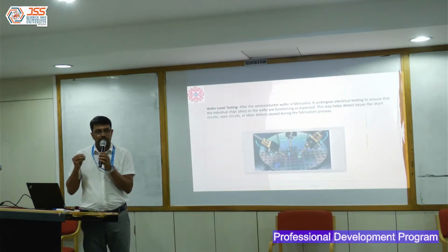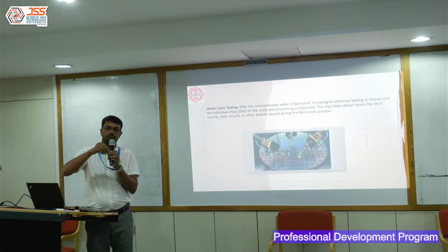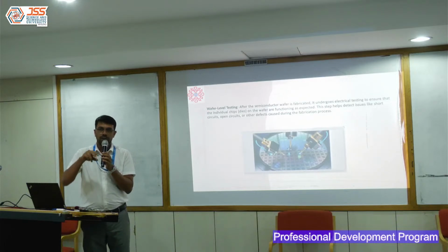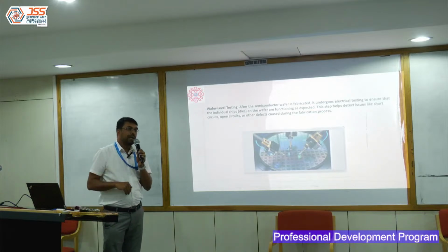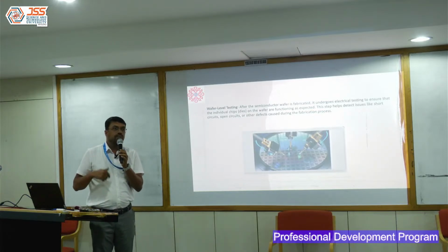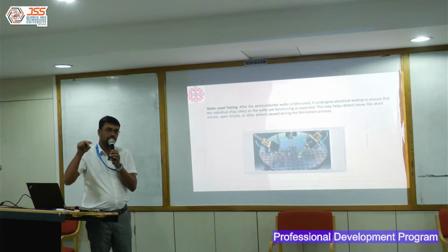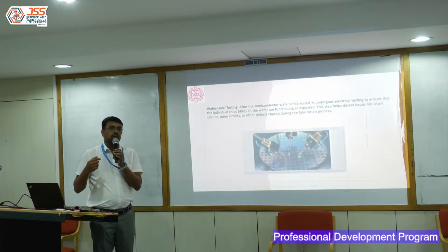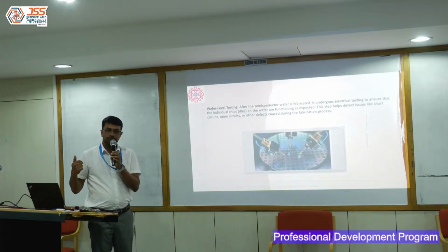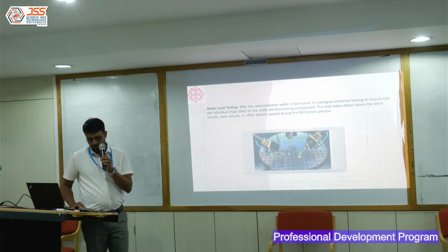Again, during packaging also, you can have certain defects introduced because packaging is all about making those connections to the leads and all. So once it comes back from packaging, we run the packaging test, which is again the same set of patterns run on the packaged part. Any part which passes, you can call it a good part which can be shipped to the customer. Anything which fails, normally we discard it.